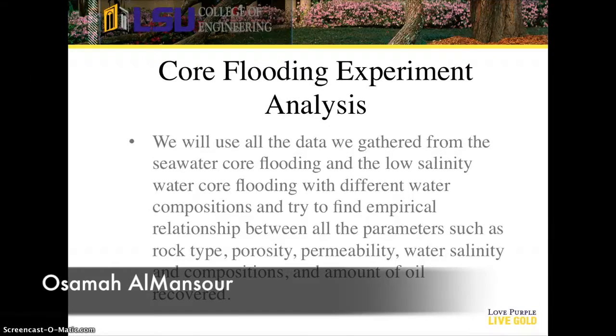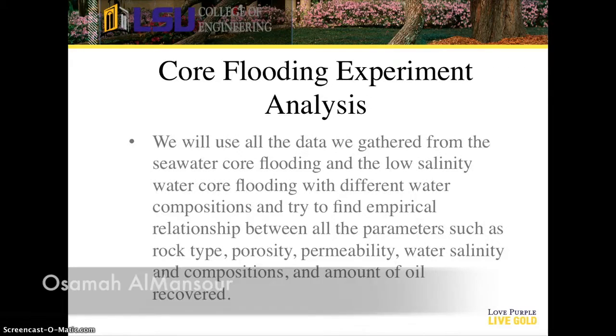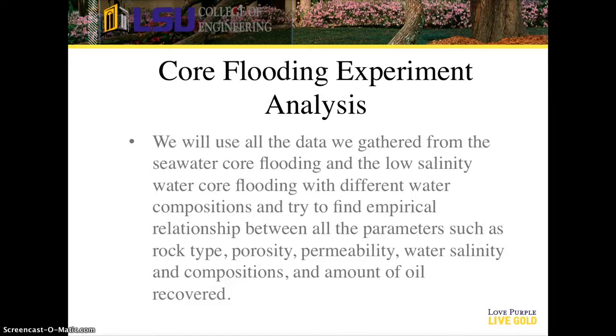Core flooding experiment analysis. We want to analyze the differences in the relative permeability curves and the residual oil saturation between all the core samples to try to identify all the properties that affect the residual oil saturation. And then we will try to develop an empirical relationship between the different rock properties and water properties with the percent improvement in oil recovery.